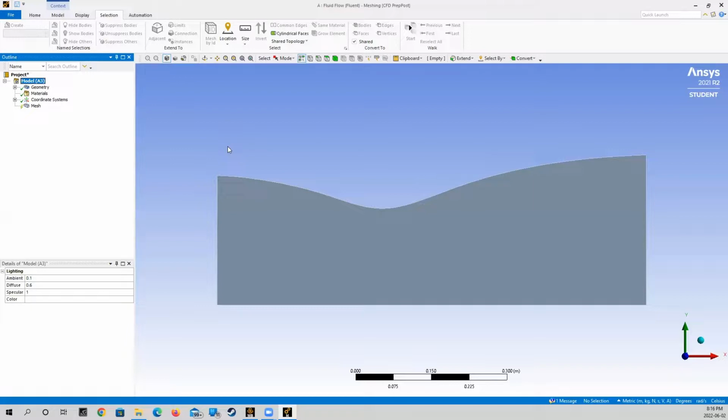Now, there are many different ways that we can actually build the mesh for this model. There are ways that require us to determine the number of divisions we want along the spline and the axis of symmetry. And then based on that information, ANSYS will go ahead and create a mesh for us. Or there's ways that require us to split the surface with different lines, and we determine the number of divisions we want along each of those lines. This could be a good method to concentrate more of the elements around the throat of the nozzle where you'll have more interesting information occurring.